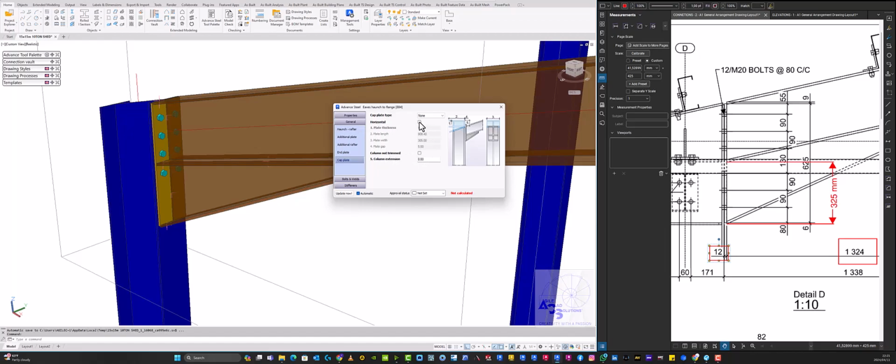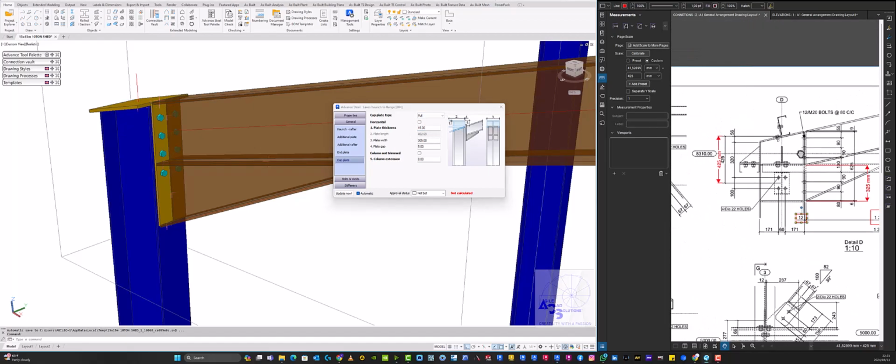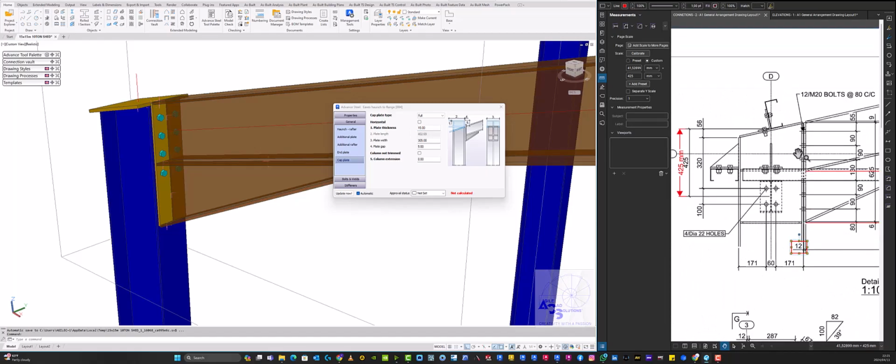So then we say either cap plate none, half, full, or by value. We want by full. And then the plate thickness, let's see if it has been indicated there, but that should be an 8 plate. That should be an 8 mil plate. All right. Then we go to plate width.